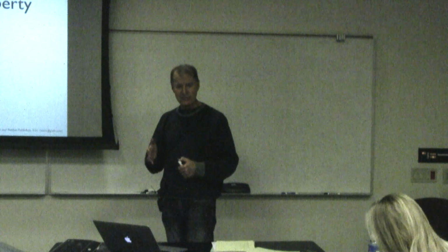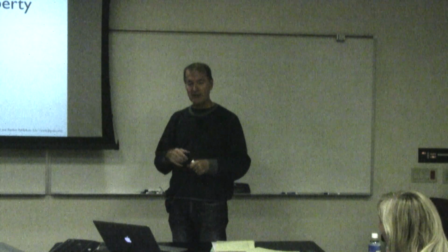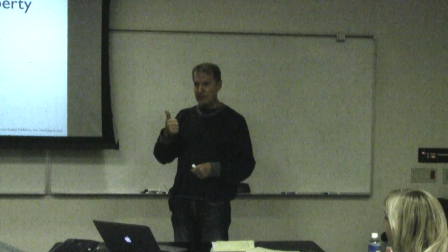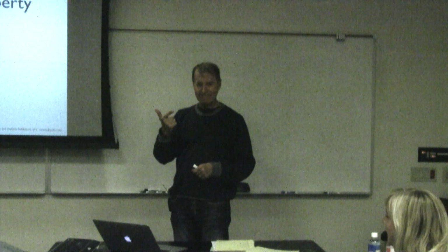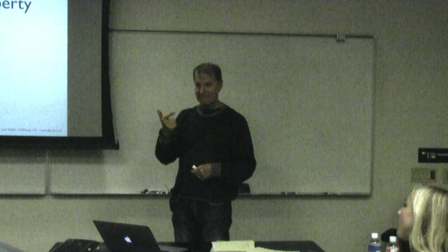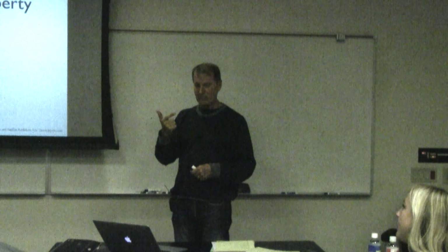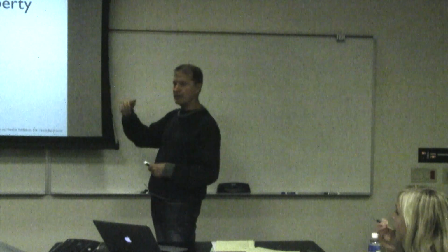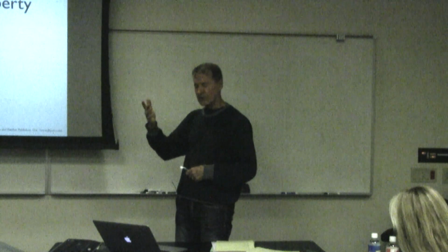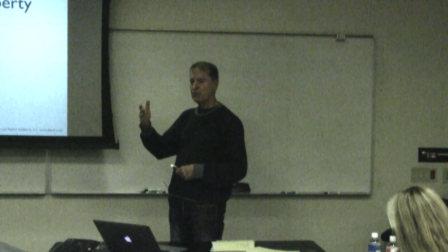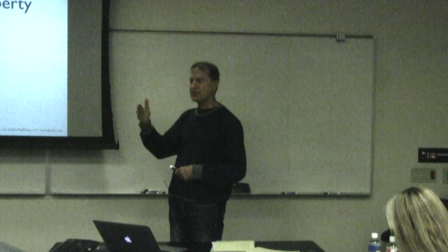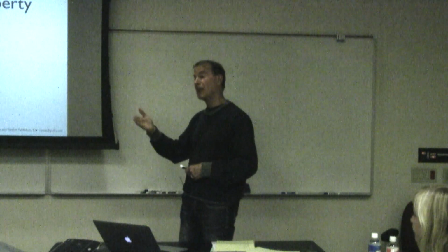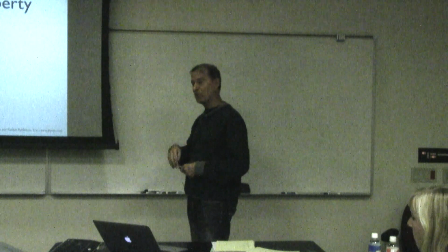So to specify a combinational circuit, what are the 3 ways? Truth table. Boolean algebraic expression. And what's the third one? Logic diagram. Okay, so what we did here was the Boolean and the truth table. With the truth table, you give the output for all possible combinations of the input, because the output depends only on the input. So there's no ambiguity involved there at all.